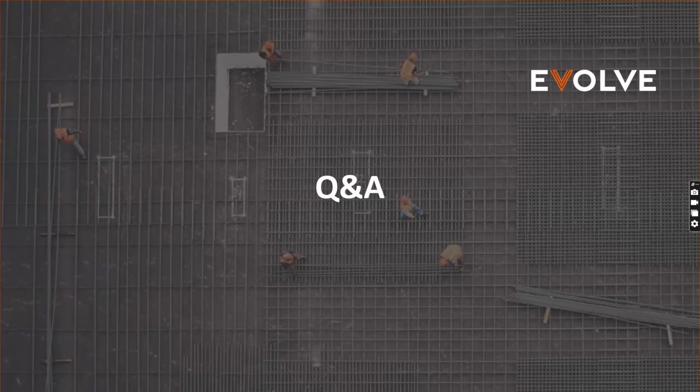Got a question here that says, how does a large conduit ID file affect the performance of the model? That's a great question. It really doesn't, in the sense that having a large amount of conduit runs itself does not affect the performance of the model at all. What that will mean though is that your model is probably larger. And then when you want to pull your lengths, it's going to take a little longer to query the model and get those lengths.